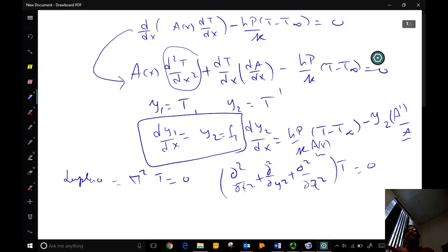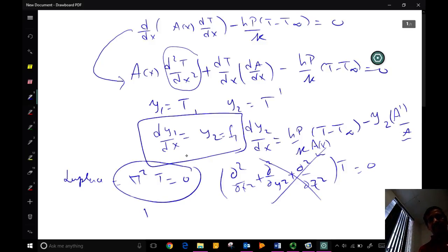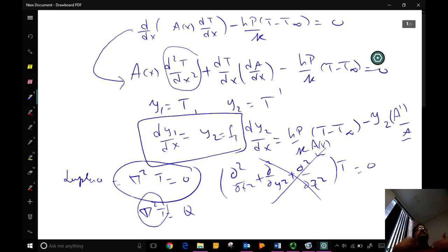This is why it's easy to generalize in COMSOL, right? Because it solves this problem. In 1D, you don't have this. You just have one-dimensional variation. A Poisson equation is the same: del square T equals some q. If you have a constant on the right hand side that's not 0, then you call that a Poisson equation. So if this operator is a one-dimensional operator, that's our template. You need to find a matching template in COMSOL to set up your problem.